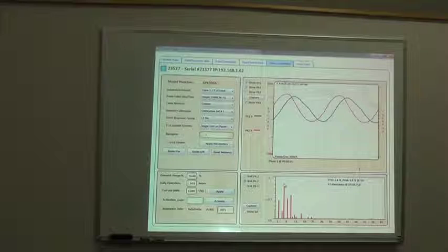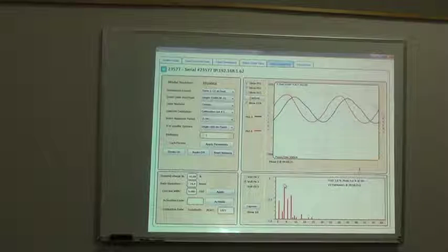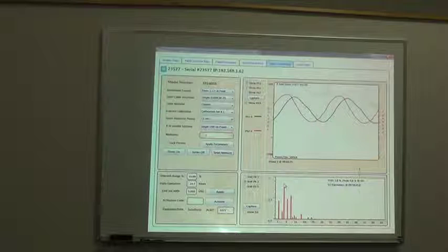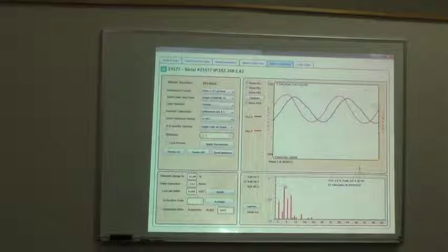In this location, it was the worst I've ever seen. First of all, the motor was gigantic. It was one of those car crushers. They were literally taking metal and chipping it, and so the currents were huge, humongous. And the cabling was so bad that after they installed it, the next day they fired the electrician. On a motor, if I can recall, it was drawing something like 2,000 amps, and they were using basically a single 350 MCM cable.